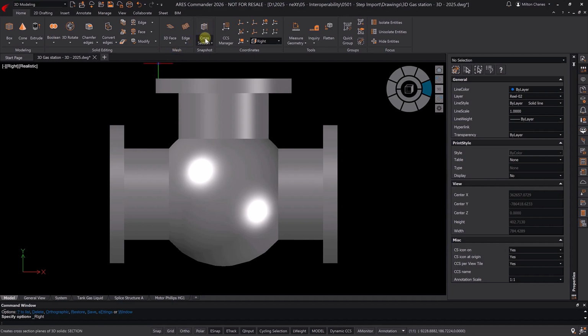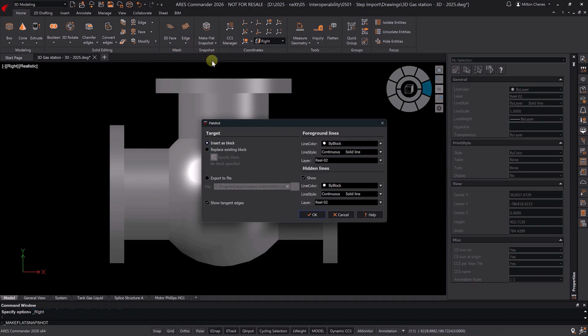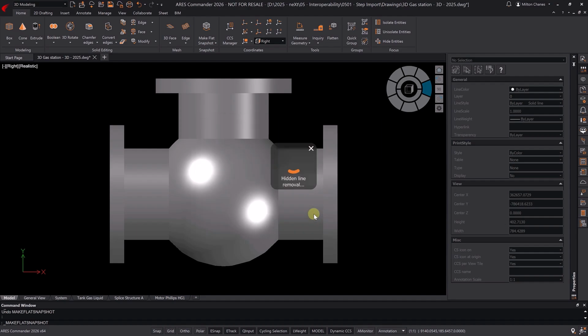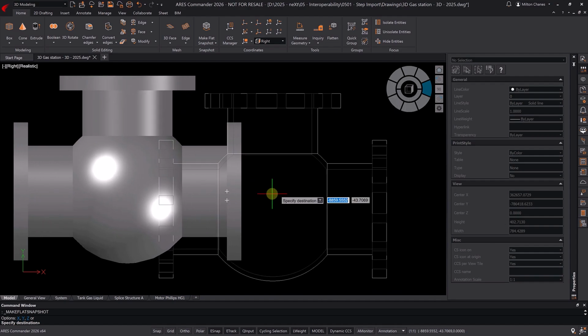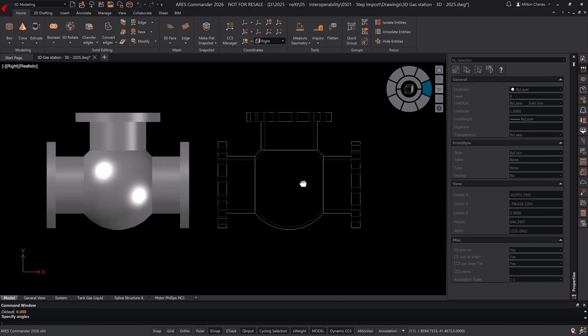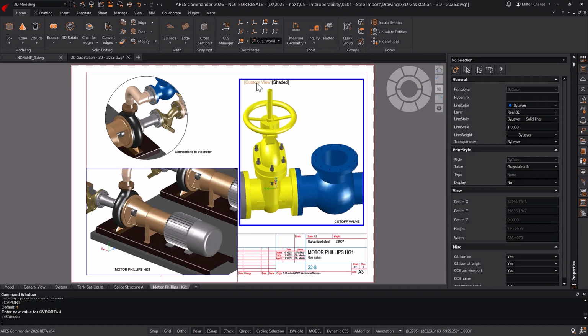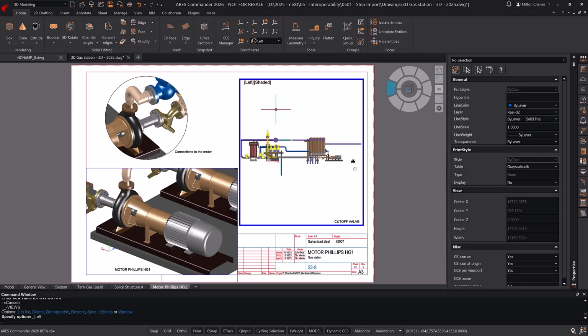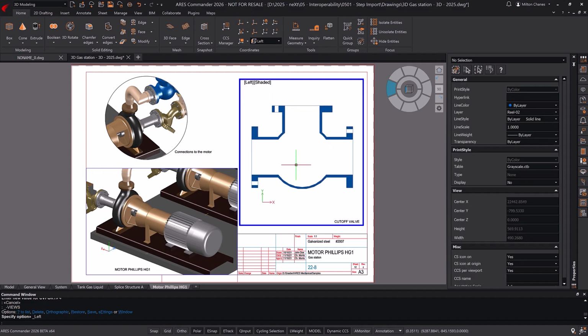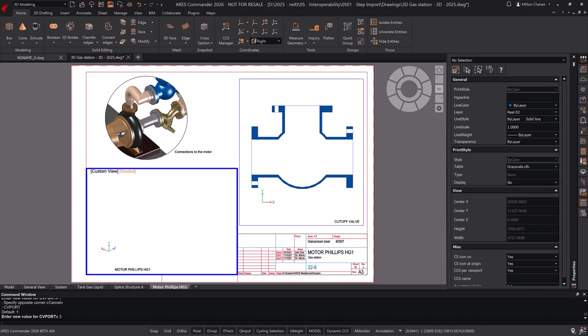On the other hand, if the view is frontal or lateral, the result will be an elevation drawing. The resulting frame is created as an editable block, with the option to show or hide hidden lines. Additionally, it is possible to assign them a specific layer, color, or even a custom line type. From Paper Space, we can set up a sheet to combine 2D and 3D drawings through multiple views, and create detailed views of a specific part.